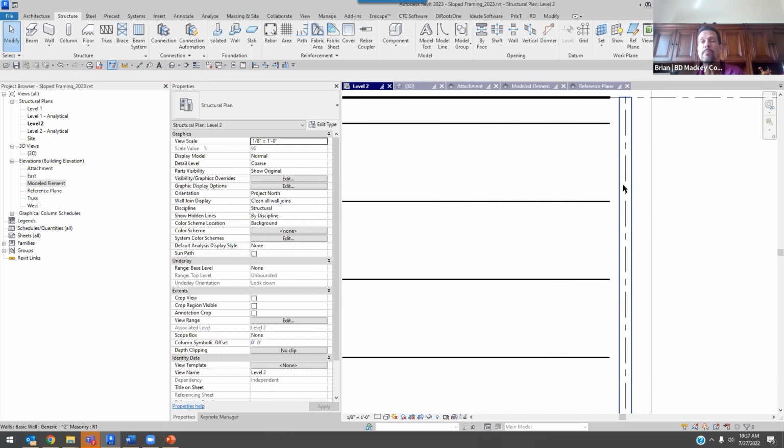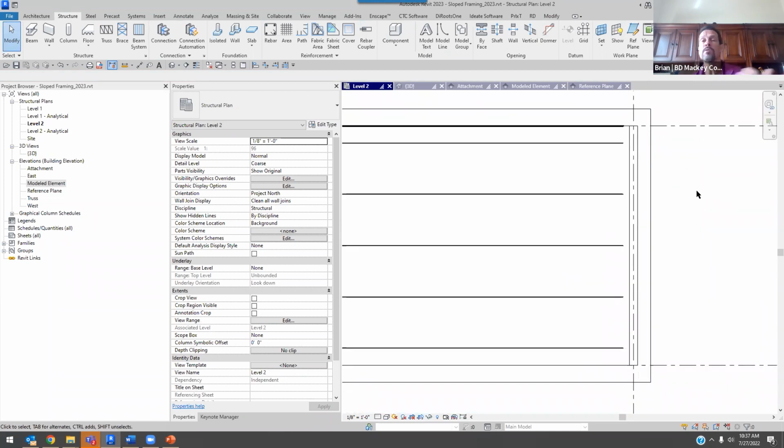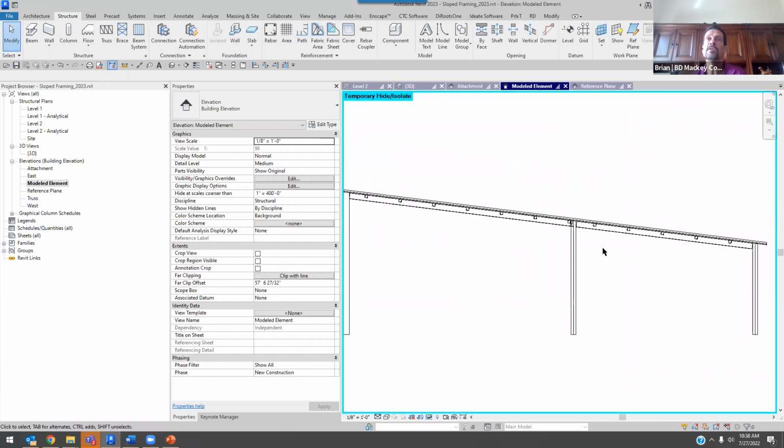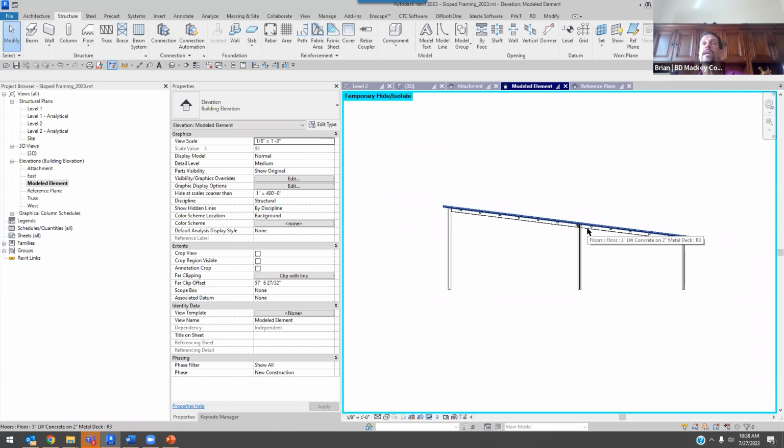But I use the wall for the beam system or anything like that. By using all of these reference tools, I can pull that beam wherever I wanted it to and start controlling that scenario. So the question did come up: when I am going through and attaching all of these elements to the roof, can I do it to the architectural model? Unfortunately, no. I can't attach columns or walls to the architectural model roof.